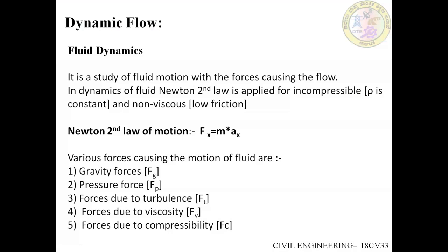Incompressible fluid means the density, that is rho, is constant, and non-viscous fluid means it has little or no friction. We all know what Newton's second law of motion is: force is equal to mass into acceleration. Here I have considered the direction of x, hence Fx, the force acting on a fluid element in the direction of x, is equal to the mass of the fluid element into acceleration